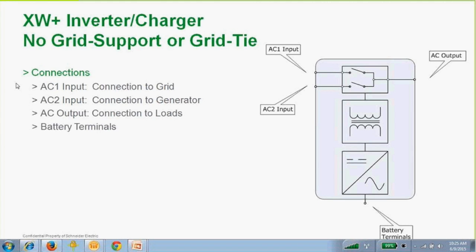It'll say, yes, I see there's an input, I see grid, and then it'll verify its quality, its voltage and frequency, and once it does that, it will close the relay, the top one there in this case of the grid, and it'll pass that energy on through the relay out to the loads and run the loads directly with the grid. Key note here is that this is not a power conditioning device, so whatever you have coming in is going to be the same thing going out.